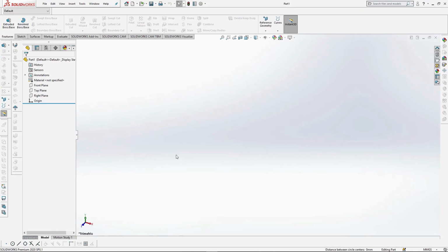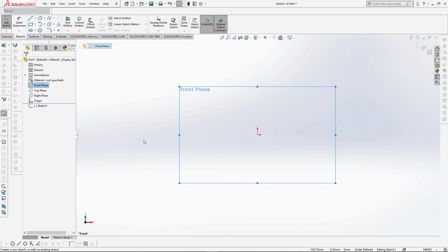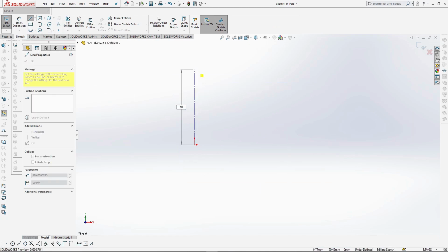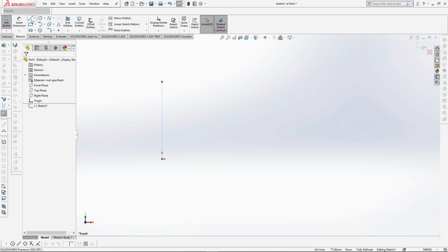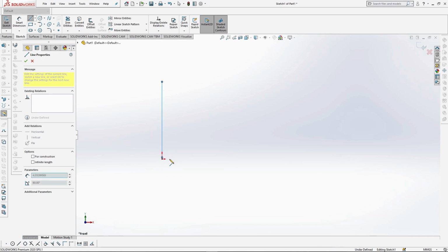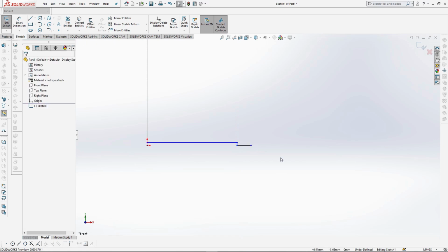The first thing I need to do is to create the bowl model that I want to mould. Sketching onto the front plane, use the centre line to draw a 50mm vertical line from the axis. Using the line tool, sketch back down over the top of the line by 49mm and horizontally by 32.5mm. Down by 1mm, level with the axis, then horizontally again by 5mm. This will be the foot ring of the bowl.